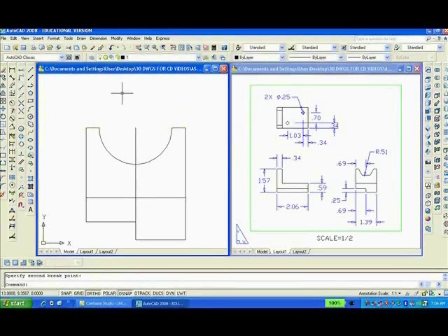And we'll want to fillet it with a radius of 0. This intersection here, it didn't erase or trim it. That means the only way we can get rid of it is to erase it. So E, enter, erase. Now to zoom previous,